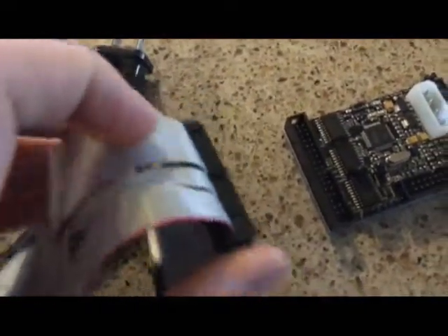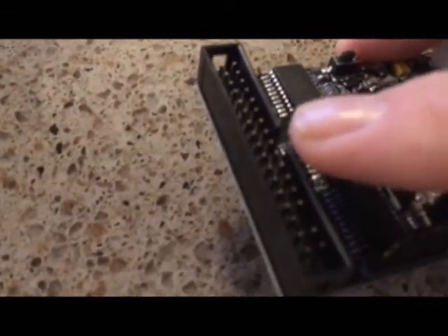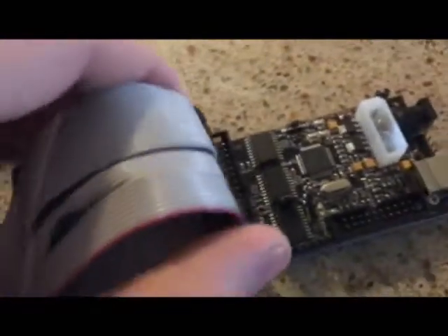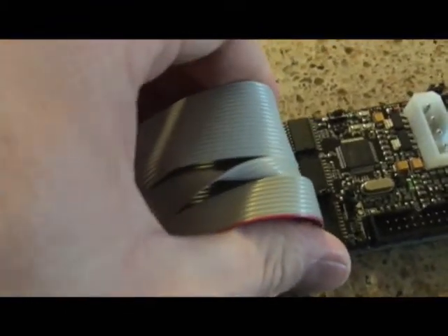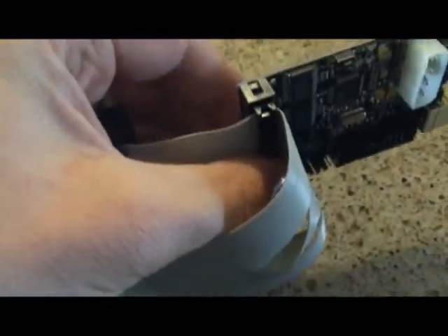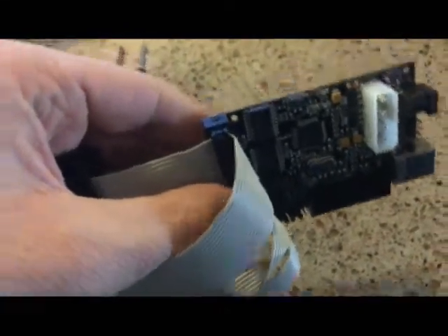It's going to be the same concept for when we plug in the other end of our data cable into the Kryoflux. As before, we can observe that, it's a little harder to see where it's dark, but there's another notch right in there along the top, and we have another notch in the other end of our data cable. So go ahead and plug that in, like so, and make sure that the connection is firm. If you mess up this cable, you risk frying the board, and then you'll have to buy another one.